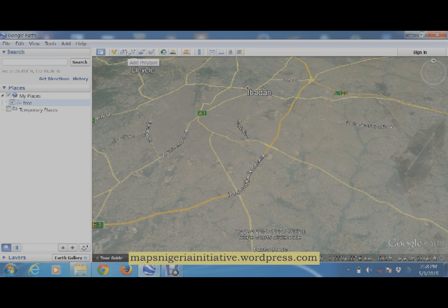So what I'll do is to calibrate it. Let me put in that spot here. You always start with your latitude first when you are inputting points into Google Earth, then a comma, then the next one, which is 3.76908. This is how you put it in.